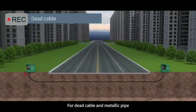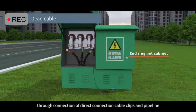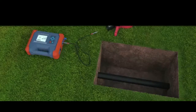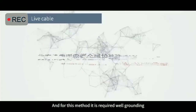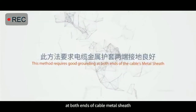For dead cable and metallic pipe, a complete loop is formed through a connection of direct connection cable, clips, and pipeline by the reflux of the earth. For live cable, coupling the signal to the cable by clamps is needed. And for this method, it is required to have good grounding at both ends of the cable metal sheath.